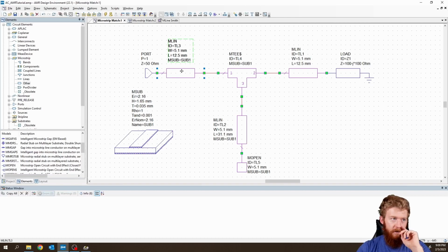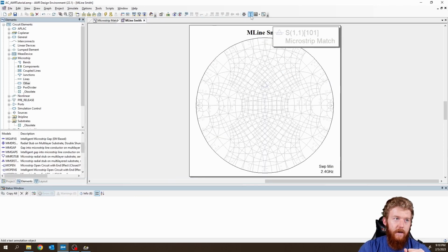So now, what we're going to want to be changing, we know that this ideally isn't going to have any impact here. This transmission line is 50 ohms, and we're expecting it to be 50 ohms regardless if we're matched to 50 ohms here. So let's go ahead and make this pretty long. Let's say 25. Now, we know that we want these to stay at 50 ohms, so we don't want to change the width, but we can change the lengths. And we can change the lengths here. This may not be the most exact solution that there is, but it does work to get things going pretty well, pretty easily.